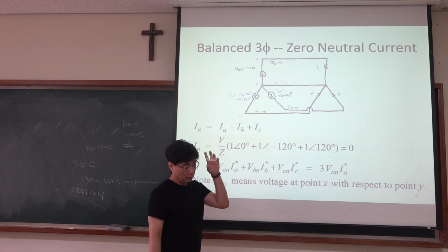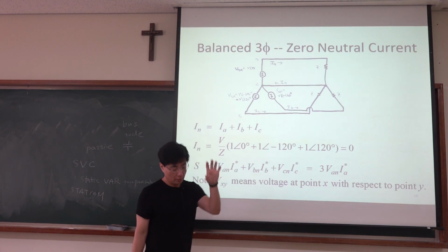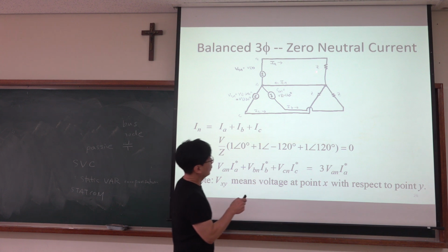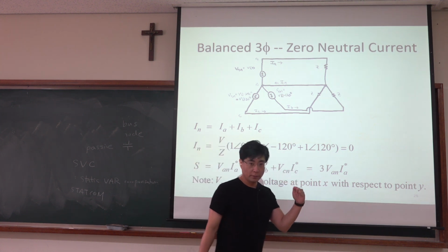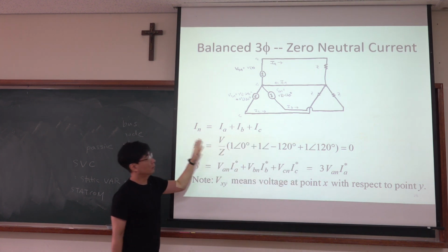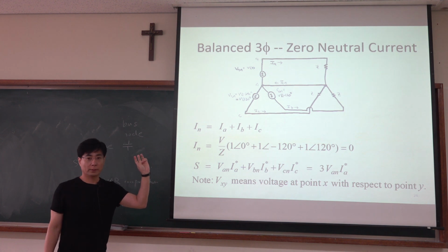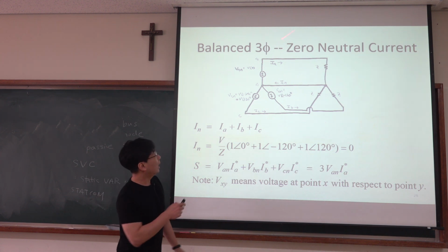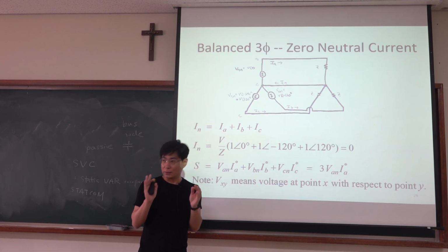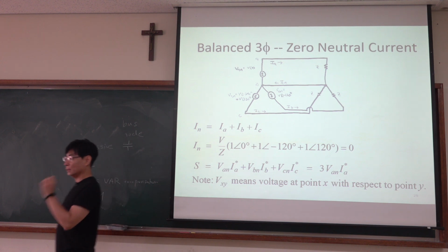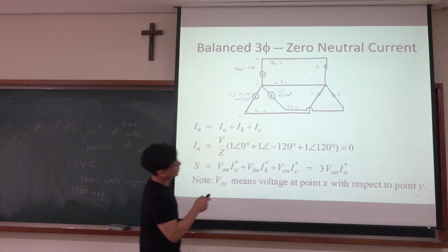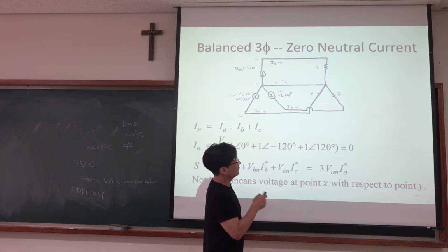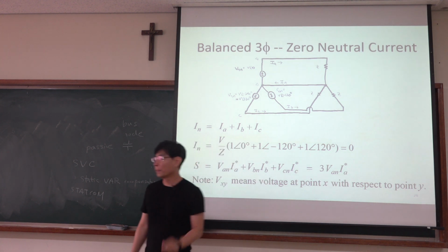Voltage magnitude VA, VB, VC are same, and this load impedance are same, Z. Then this is called a balanced three-phase system. Okay. Then what is unbalanced three-phase system? Well, IA may be different from IB slightly, or different from IC, or the load impedance, this ZA, ZB, ZC are slightly different.